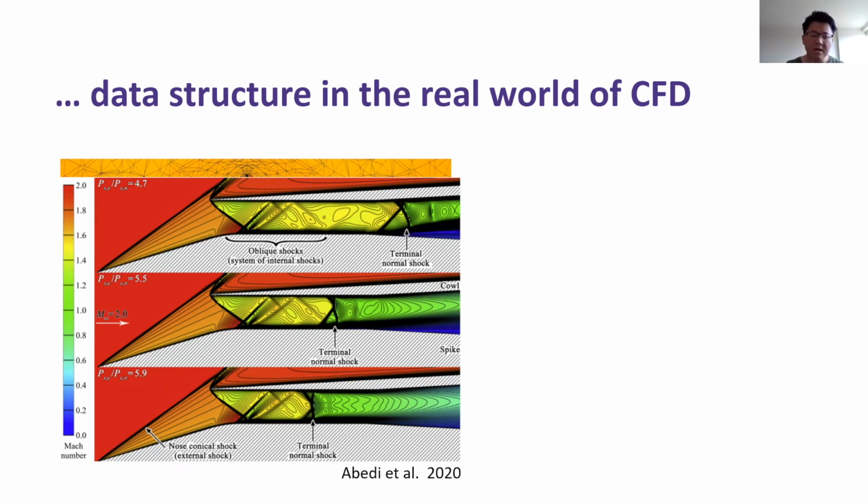So that means if you have different parameters, the mesh will be different. Therefore, if your goal is to come up with a surrogate model that is able to predict what is going to happen for unseen operating conditions somewhere in between, you cannot really use singular value decomposition to reduce the dimensionality of the flow field, because different training data has different mesh sizes and different mesh topology.